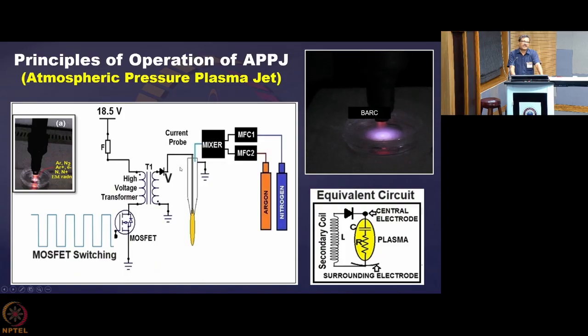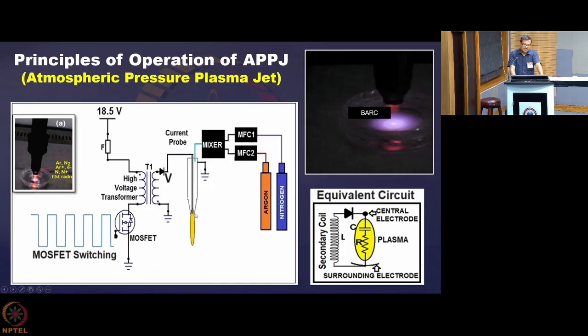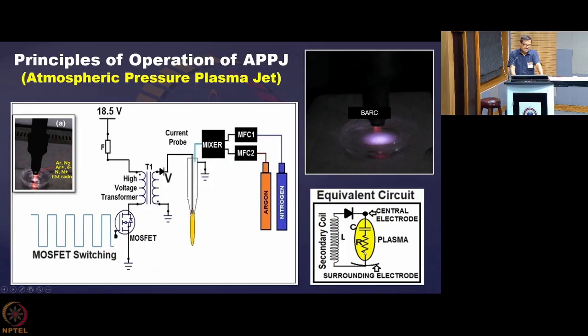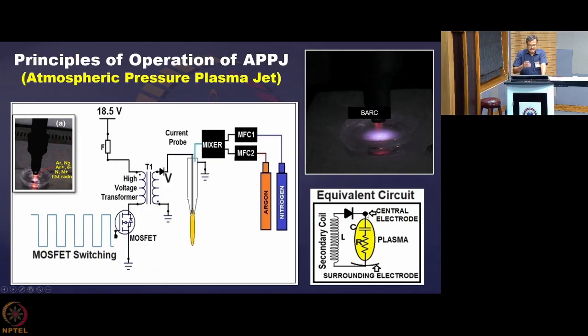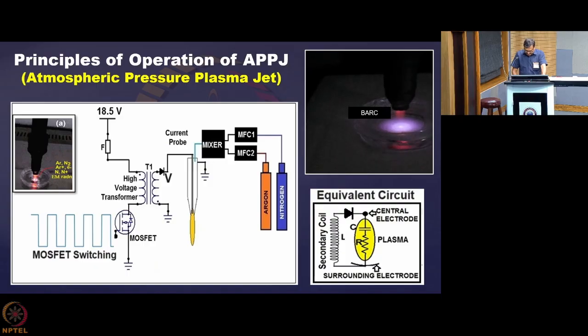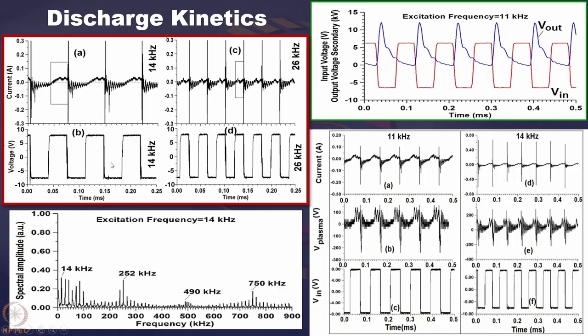So now it is very much clear that once a very high voltage is applied across these two electrodes, a plasma is generated, then the circuit is complete, and an LCR circuit is formed, which, as per the physics that you have studied in your graduation classes, we know starts oscillating, and this is exactly what we are seeing here.